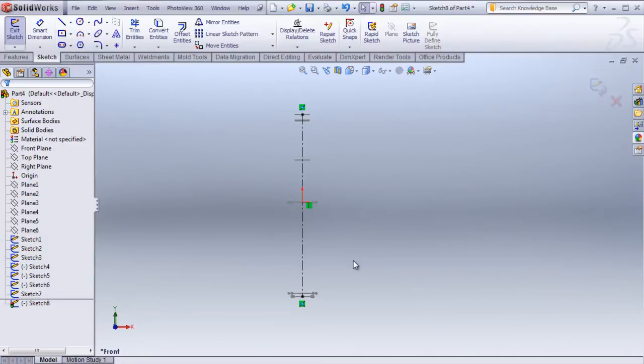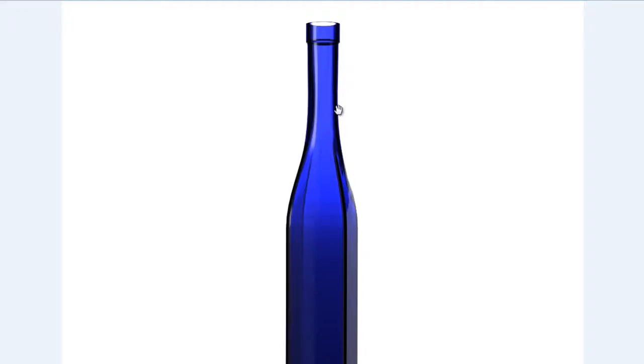Now after developing this, I'm still going to develop a profile out here. Just to avoid any other unwanted relationships, I'm going to hide all the previous sketches that I developed and leave only one out there. Now if we look very carefully at the image, the profile will be one horizontal straight line, another horizontal, another straight, up till here, and from here to here there is a spline, which is going to be different than the line.